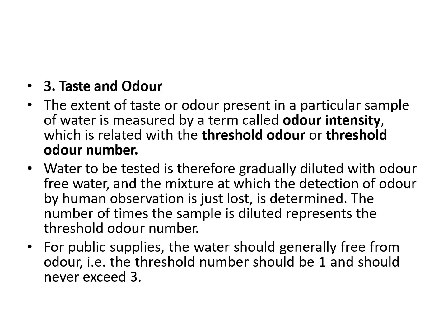Then taste and odor. The taste or odor present in a particular sample of water is measured in terms of odor intensity. The water sample is tested and gradually diluted with odor-free water, and the mixture at which the detection of odor by human observation is just lost is determined. For public supply, the water should generally be free from odor. That is, the threshold number should be 1 and should not exceed 3.